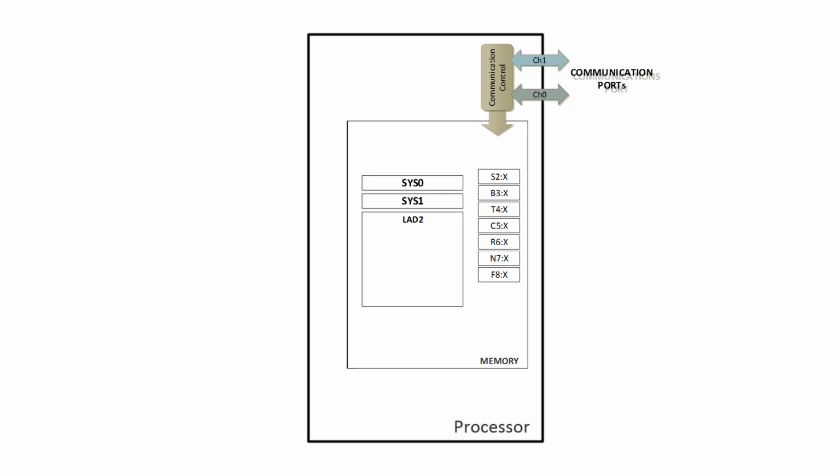Inside of the memory, when we download something, remember that memory is just 130,000 or so individual bits, electronic devices that can represent 2 states, on, off, 0 or 1. And there's nothing different between one bit and another out of the 130-some thousand bits, or 8,192 16-bit words. It's just memory. It's like a section of land, and there's nothing on that land except it's flat clay and it's covered with grass and weeds. 1 square foot is the same as another.